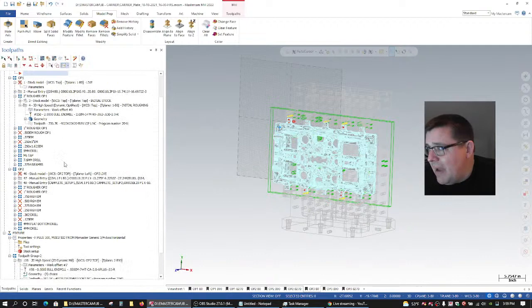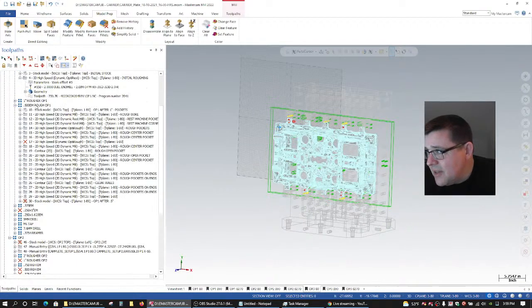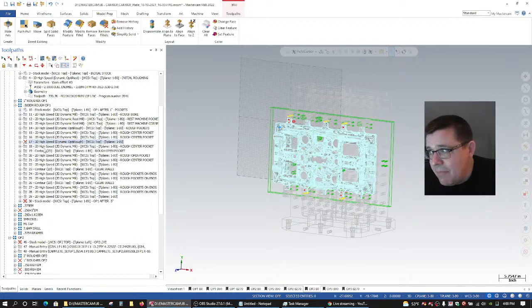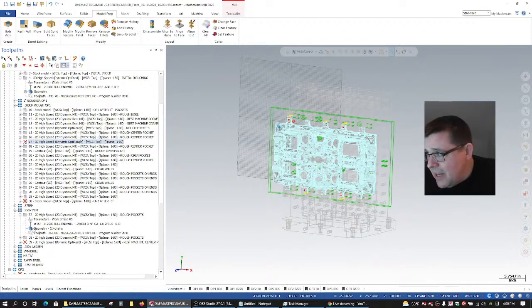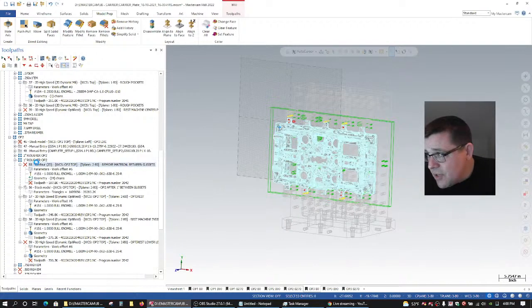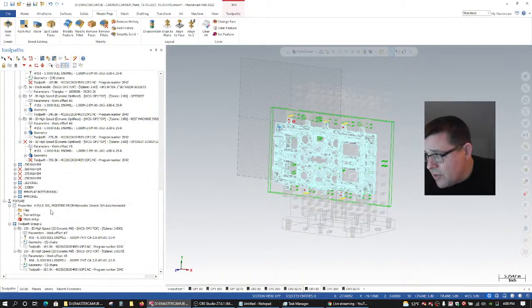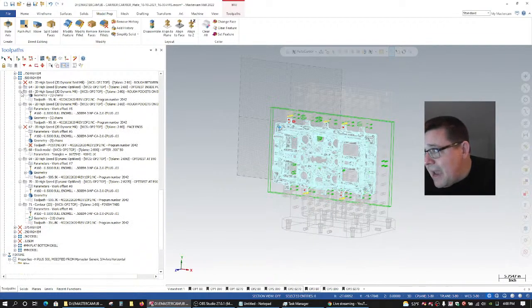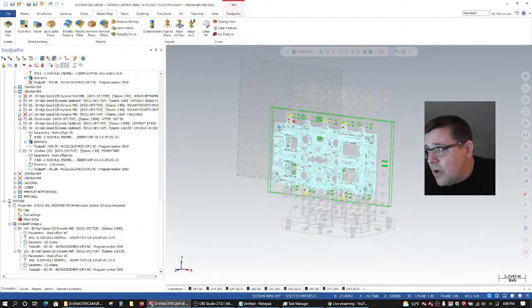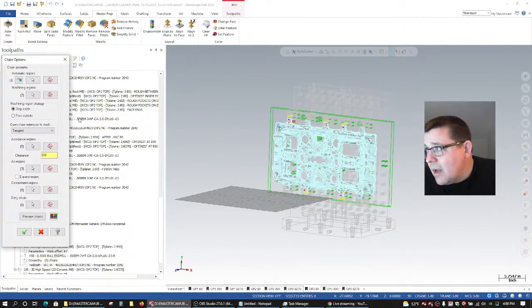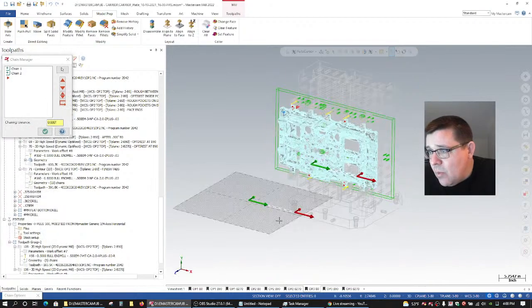So if we go back to our toolpaths, what we'll see here, like this 500 ml, this is a 3D high-speed dynamic OptiRough, and my guess is the boundary got messed up. And then we've got a 250 ml here. It's another 3D dynamic OptiRough that got messed with. Here's a contour, so a 2D contour. Here's a 3D OptiRough, 2D high-speed dynamic mill. So some of these paths became dirty likely because the chain got broken, depending on what was actually selected.